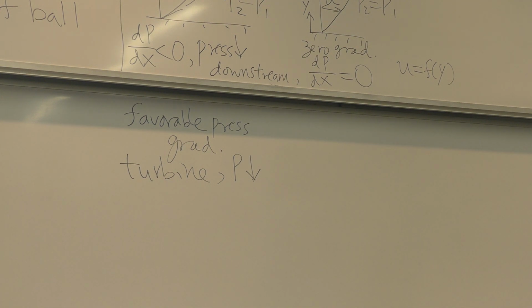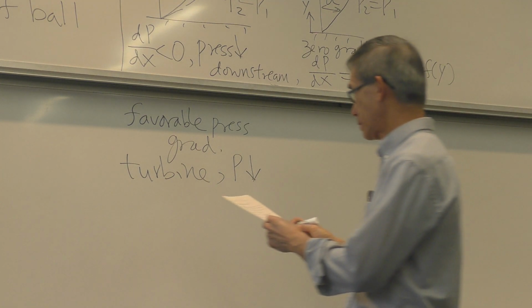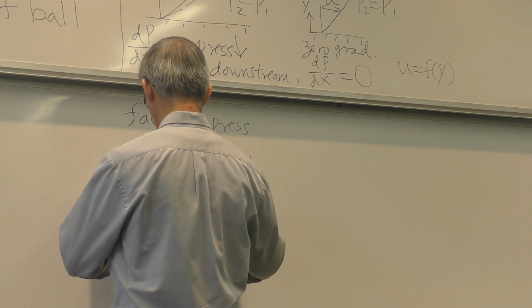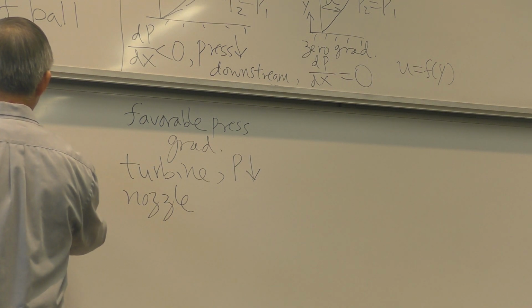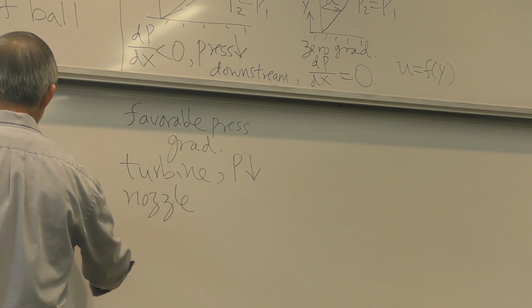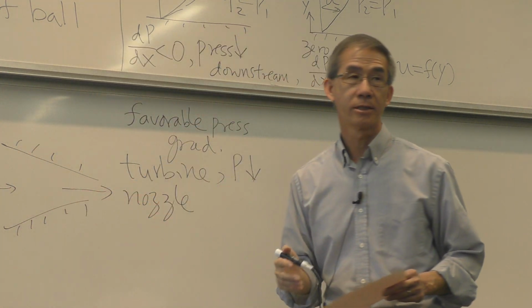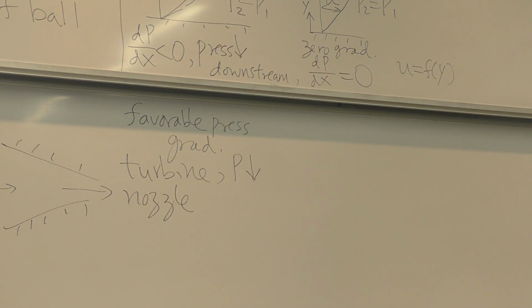The gravity head is being fed as a higher pressure through the turbine and exiting at ambient pressure. The other device is actually a nozzle, not a diffuser. A nozzle, as I remind you, is a device where the area is getting smaller because it helps to accelerate the flow, like in the aircraft engine nozzle.